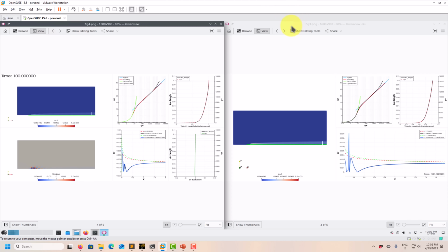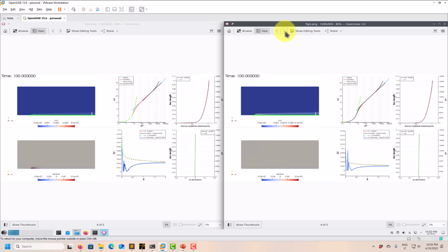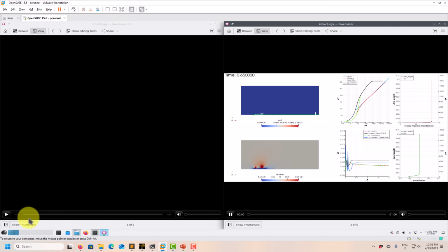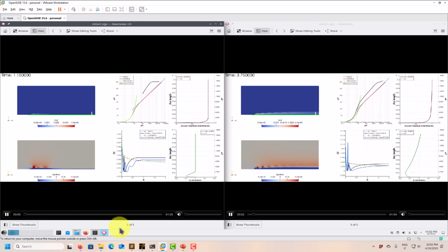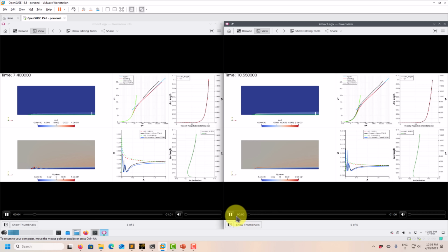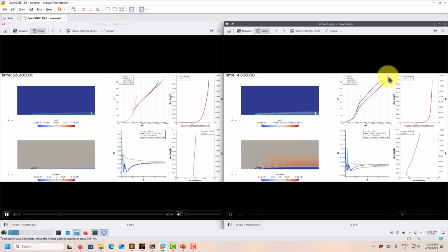Now let me check here, okay, and let me go to the movies. So play and play and play here. Go. So look at that, the wall resolving at the beginning. And again, we go to the opposite case to the K omega SST. So in the K omega SST, the low Re was resolving that fluctuation. In this case, it is the opposite. So I would expect the low Re just to resolve everything, not to diffuse everything.